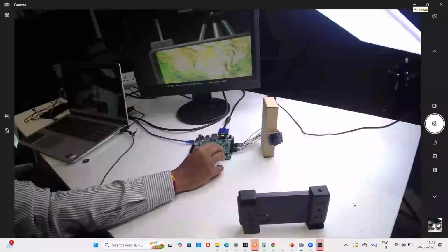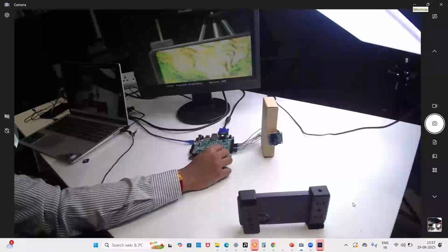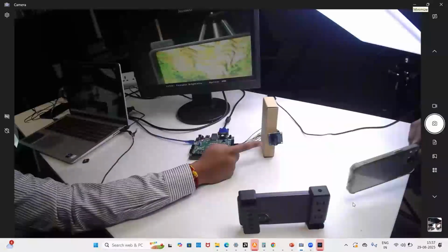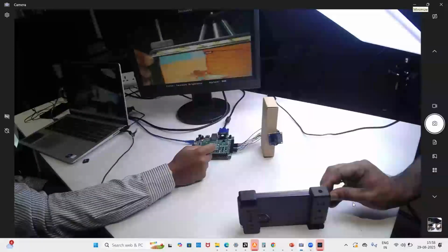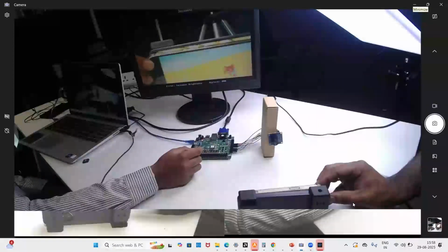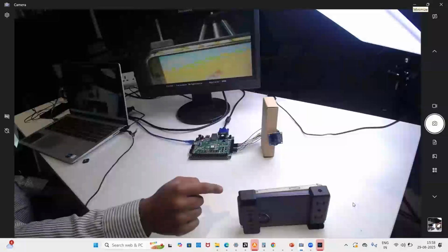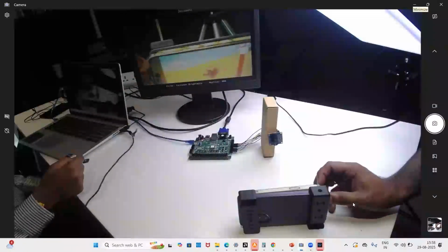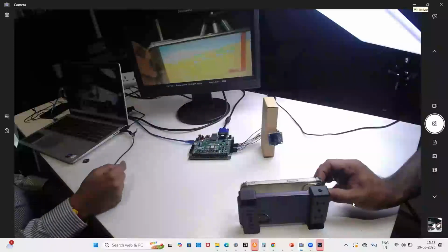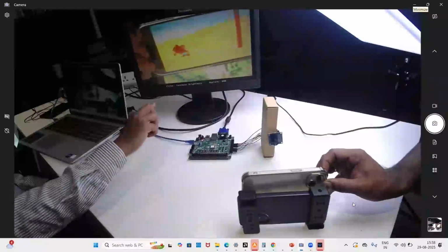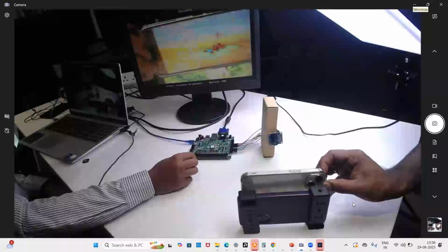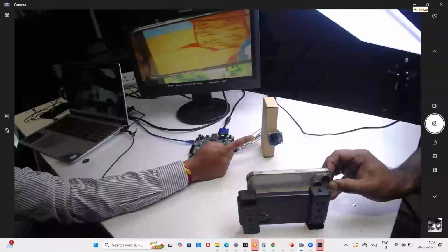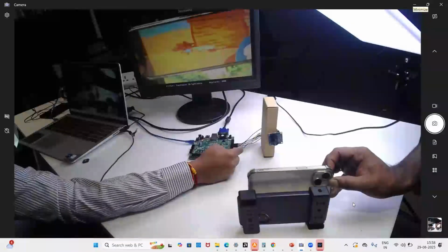So this is the increase and decrease of brightness, what you see in this code. You may see the OV7670 camera is my CMOS sensor, which is giving you the output for this. This is the increased brightness where we have done it through the RTL part. Based on this increased brightness, my CMOS OV7670 camera is capturing continuously using the I2C protocol.